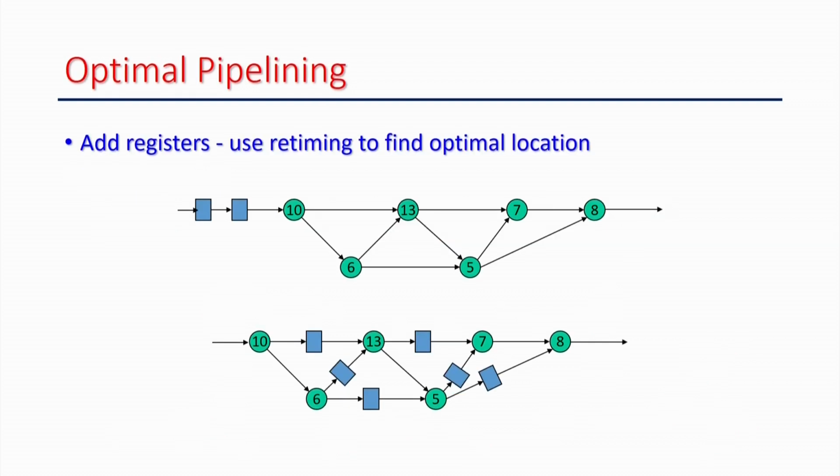Okay. So, again we can use retiming to do optimal pipelining, something like this. You can place the register at the input, and you never know how to place it, because this may be a very complex circuit, you don't know what the parallel paths are and all those things, and you can utilize retiming to do this, right. So, what I have just shown earlier, I can take this register, I can place it here and here, then I can remove this register, I can move this register to the output. I can move here, right, and then since both the inputs have registers, I can remove these registers and place them at the output, right.